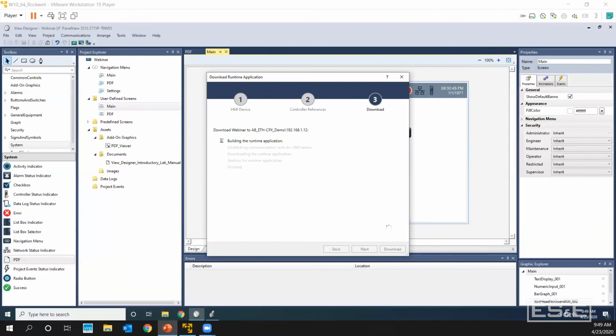One thing I really want to highlight is if you do not have the right software version of the program being created here in comparison to the firmware on the panel, it will stop right at building runtime and give you an error stating the two different firmware revisions and tell you that you must make your software match this other firmware.